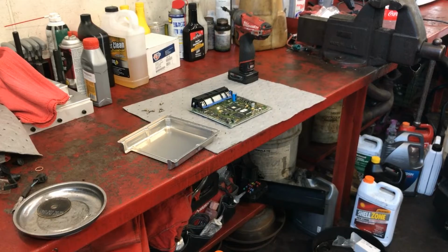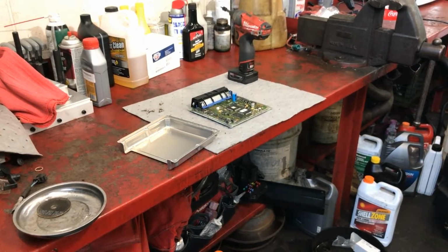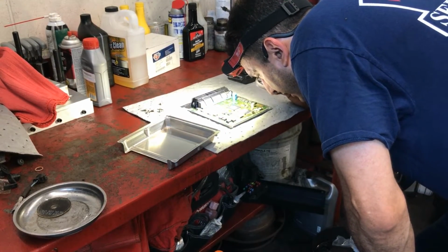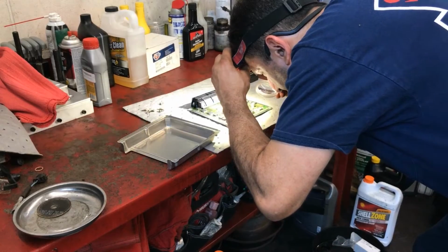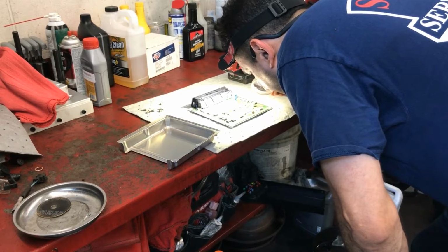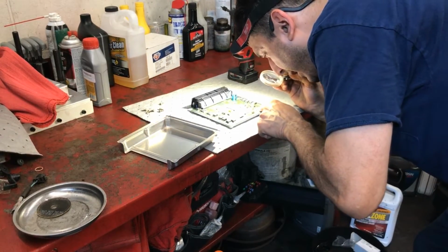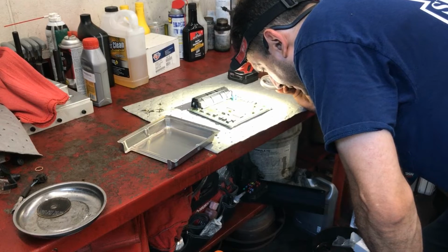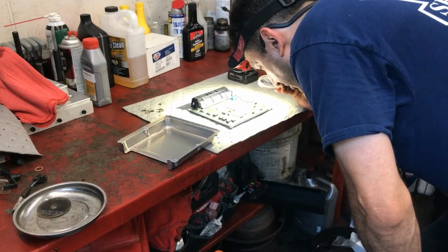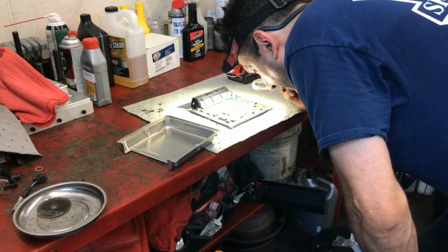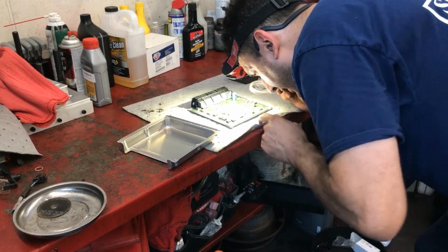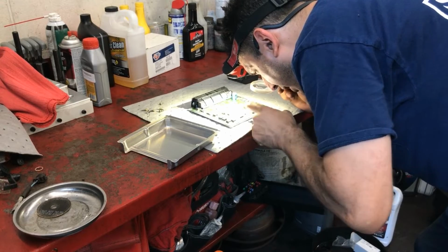All right, back in business. So I'm in the shop and I don't have my microscope here, but what I usually do is, with a good light and some glass, I can start to see if there's any damage on the board. I can see a couple of corroded legs on that chip, the one that has the sticker 188 right here. There are three capacitors that are really damaged on the right side. Those are definitely the ones that always take the heat on voltage like that. I definitely have corrosion on this main chip.